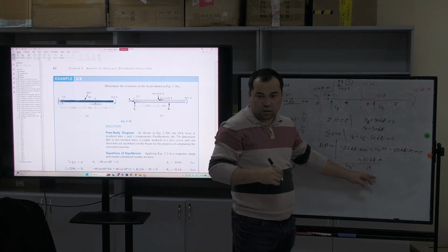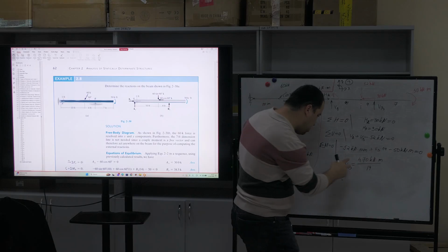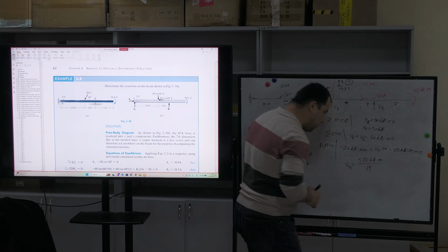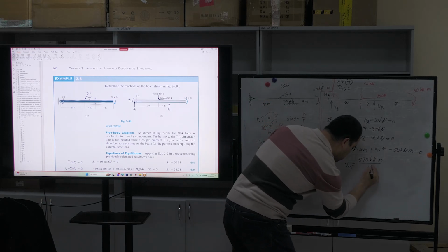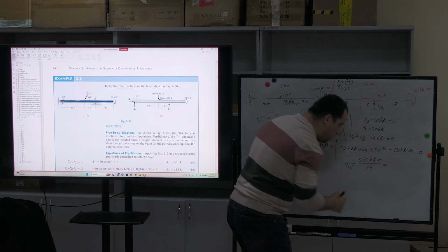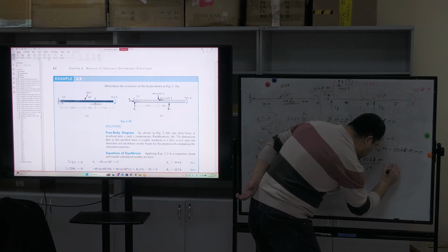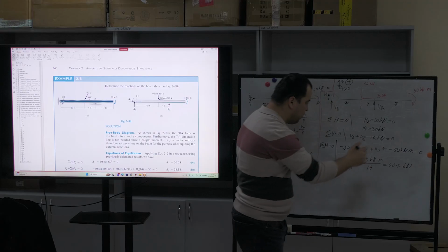Don't be in a hurry, okay? You have to write step by step. I am also hurrying. Sorry. This is 570 divided by 14. And answer? 40.7 kilonewtons. VB, almost 41 kilonewton.